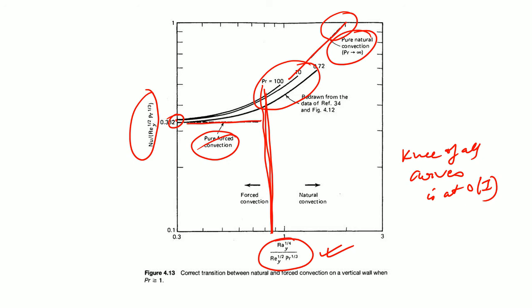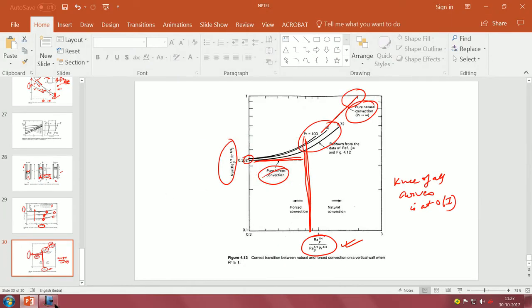We show that we can estimate the Nusselt number with sufficient accuracy and efficiency, and by doing this with asymptotes, we can actually predict which mechanism is the most dominant of the two, but we have already established what the scaling arguments are going to be. So, for Prandtl number greater than 1, this actually covers the revised scaling argument, so to say.